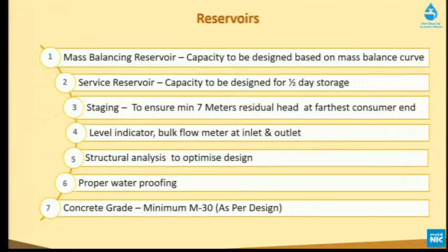Reservoir, I think this is also one of the gray areas in design. The reason is that in some places during the field visit, we found the reservoir was over-designed, while our requirement is very little. When we are designing a mass balance reservoir, depending on the mass curve, we can design the optimum capacity. Hardly does a mass balance reservoir require 1 hour or 2 hours of retention, because water is coming and flowing.